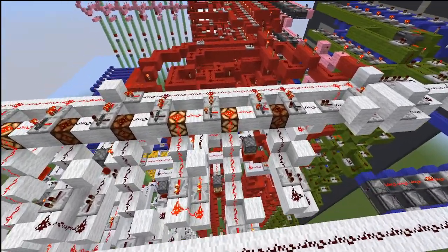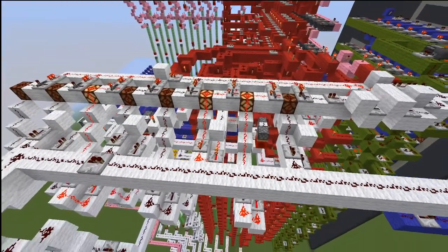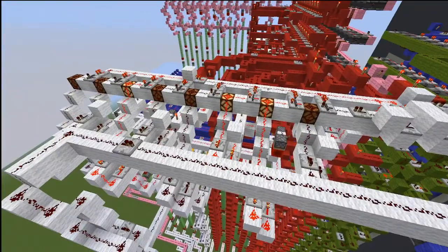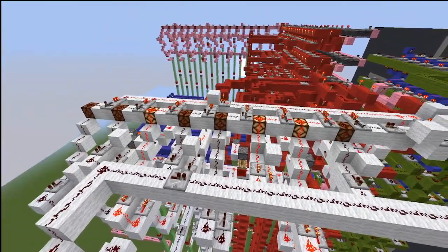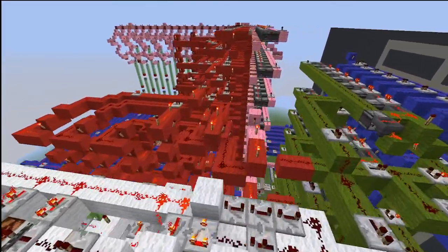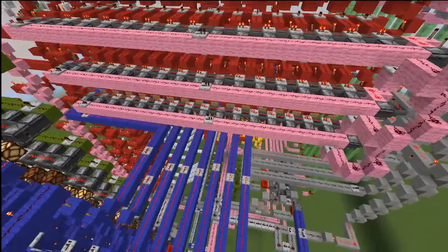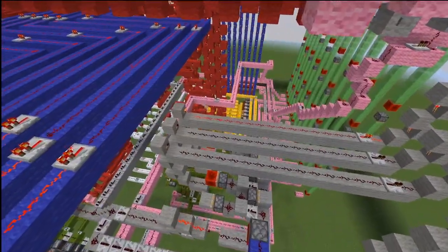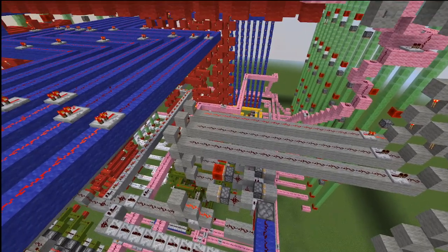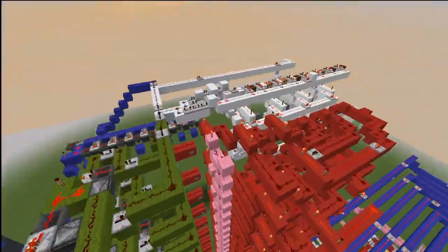And then it's going to write whatever's in prom line 6. 4 plus 2 is 6. It's going to write whatever's in prom line 6 to the address data bus here. And then it will update the B register, and then it's going to perform addition in the ALU, and then take what's in the ALU and send it to the accumulator. So it just incremented the program counter, and when it switches over, it should be writing that data from prom line 6. So we can look here.